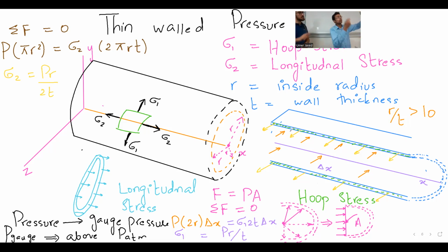Just imagine this is a Coca-Cola can. Use a knife and make a cut right through the center. Now its wall is exposed. This wall has these yellow lines coming out because the pressure is being applied in this direction. These yellow lines are our hoop stress, whereas the longitudinal stresses are along the axis of the cylinder, 90° to the hoop stresses. Another thing to remember is that shear stresses on these planes will be zero. That's why we call them principal stresses as well.